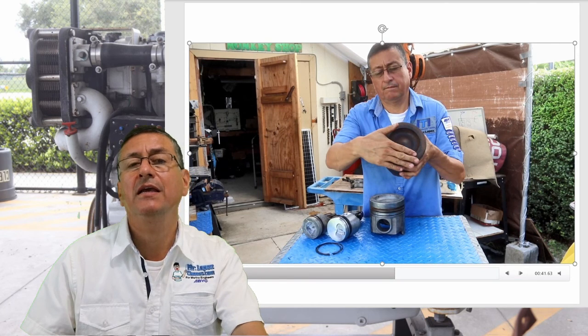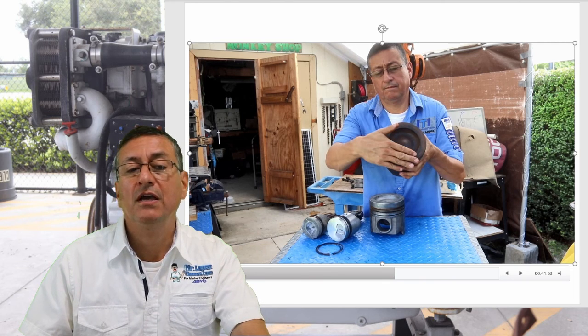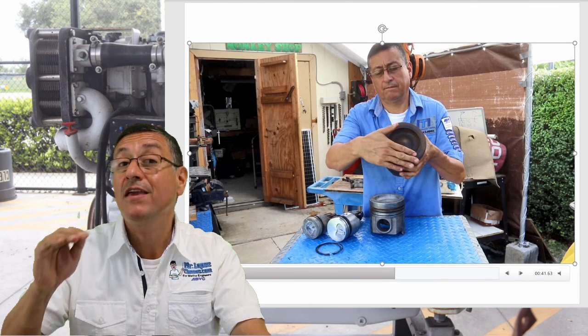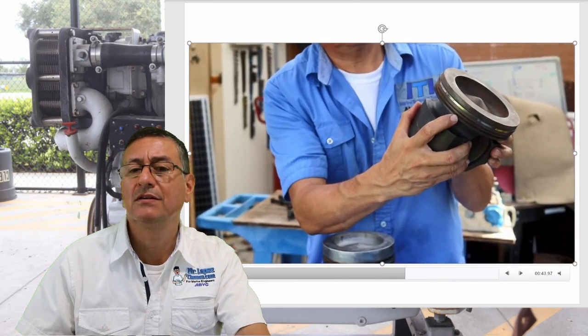This is completely in steel. It's a heavy steel: chromium, molybdenum, and vanadium. It also has inserts in other heavy material to protect the piston rings, and they have the plain bearings on the pin of the piston. Right now we are going to check that. Okay, this is the piston in steel.